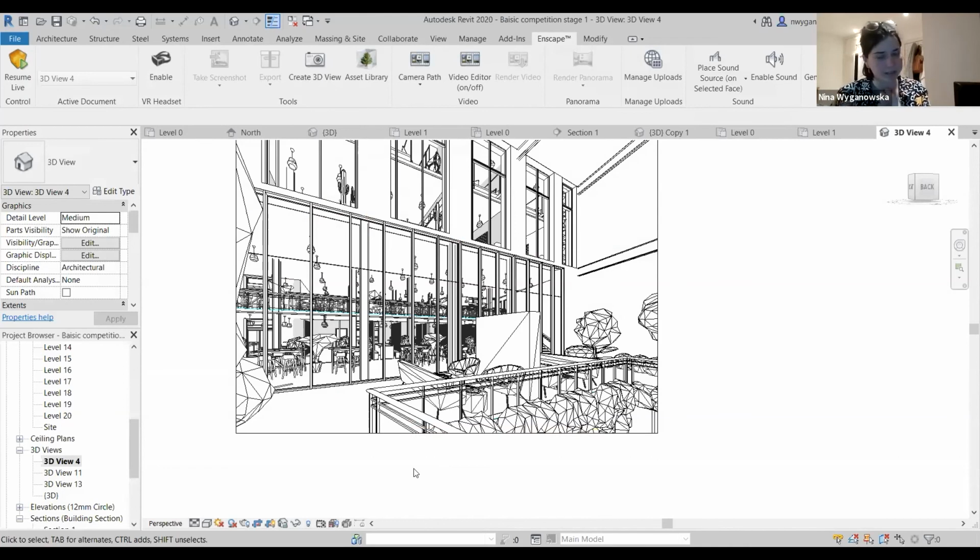For my process, I would do all the plans and all the drawings in Revit, because it gives me the opportunity to have the same changes on sections and elevations and all the other elements. But when I want to do my final drawings for uni, I normally export them into CAD and do any extra finishes in CAD.